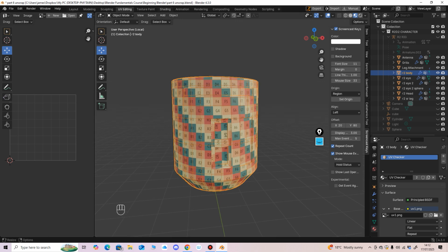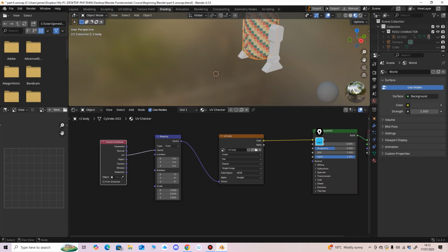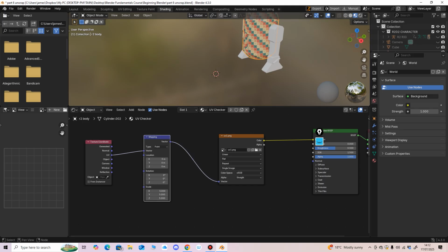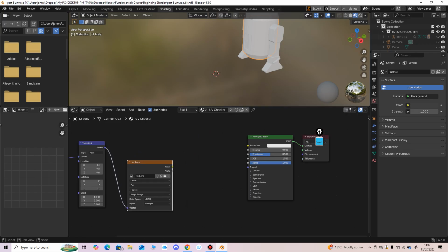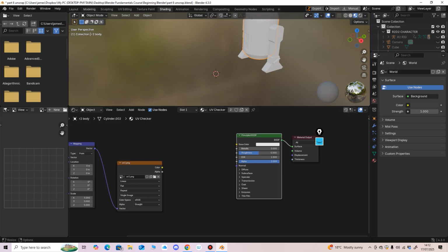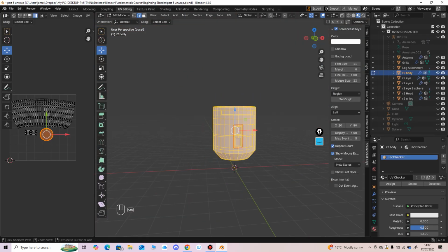There's also another way of checking. You can assign a texture like that, but we'll go more into this probably in the next lesson really. But if you hold Control, right click over that, you've cut it now. So you've got nothing now. You've got no material on it.